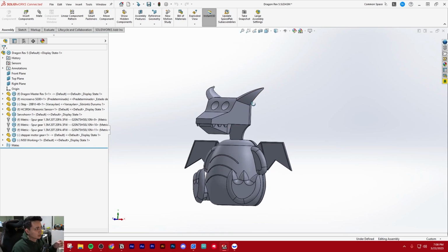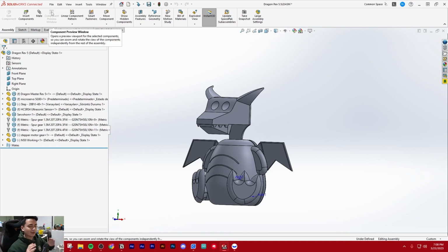And then the last thing I want to show you guys is the thing where I talked about, where you have rev 1 of files and then you bring it to rev 2 and then you still have the rev 1 files to look back on later, but you start editing in rev 2. So SolidWorks is great. It makes it super easy because you have relationships between all these features, right? So how do you make it so that all the features in this one rev 1 file are all packaged together? You bring it to rev 2 and all the rev 2 files keep their relationships to each other. You don't want those relationships to break, right?